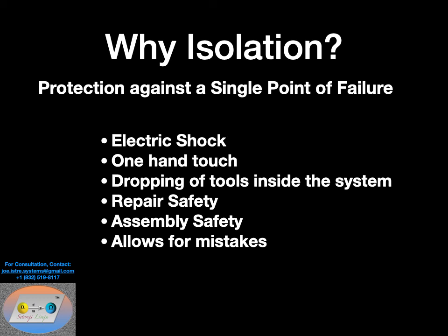And also while you're assembling the system, every module on an assembly line should be below 50 volts or 60 volts for touch safe purposes. But when you begin assembling modules into a system, you introduce the likelihood of electric shock. It's above 60 volts. So this isolation designed system is another way to protect the guys who are assembling the system after it's manufactured. All right.